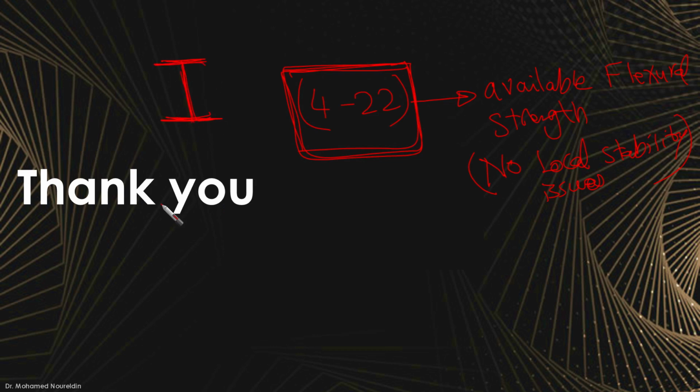If our section is having some other issues, which is local stability issues, in this case we need to reduce whatever we obtain from this table. We need to reduce it based on the E7 chapter in AISC. Okay, that's very nice, that's fine.